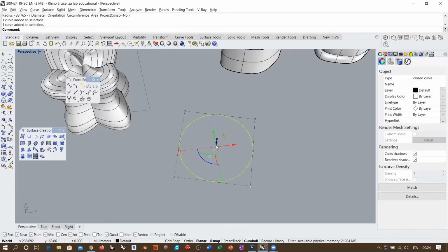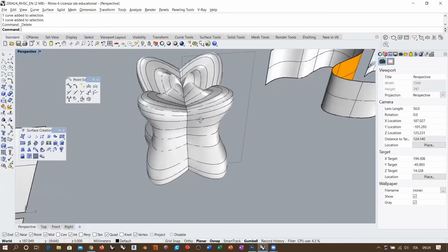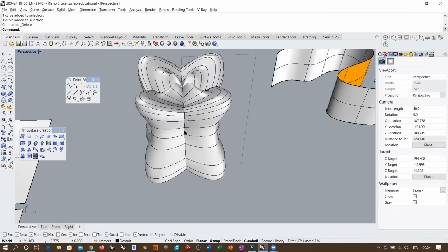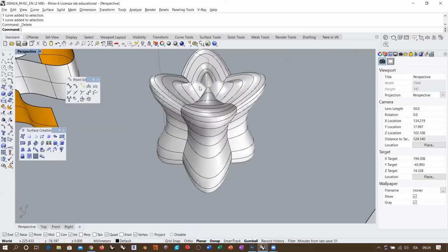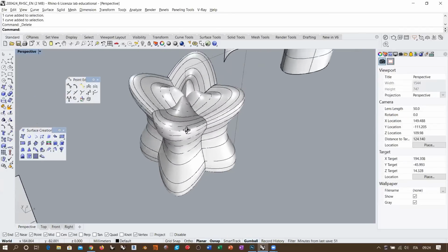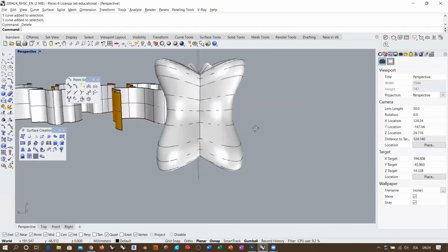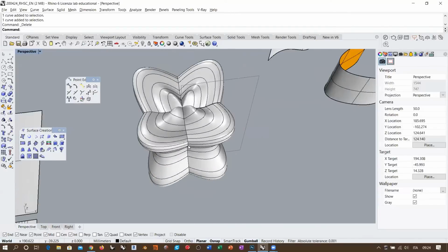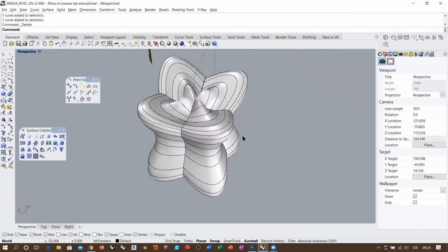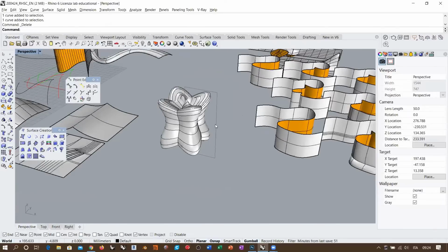Okay, and here in this surface, we saw that we had these isocurves in the quadrants of the surface. And as the horizontal rule is the circle, we also know that these are not simple isocurves, these are kink lines. And as you can see, if I try to deform, I really get some crease along the path. Okay, so this is the effect of a standard revolve execution.